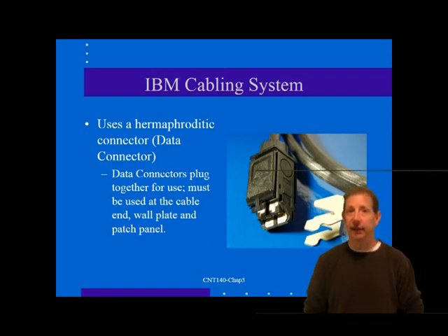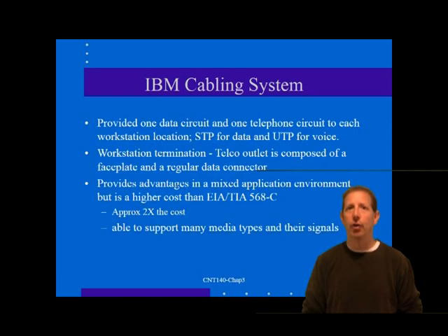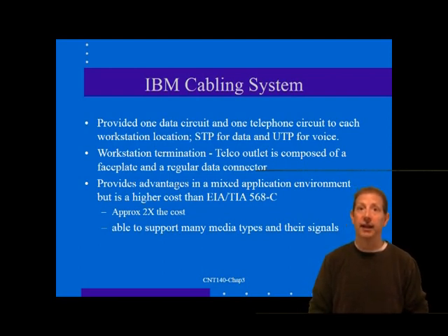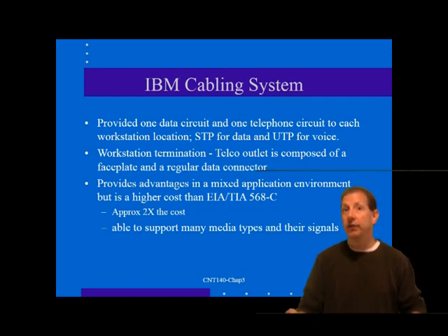The unique data connector was probably designed with token ring in mind, since that has long been IBM's network of choice. It contains a mechanical shorting bar mechanism that can electrically loop back a cable or jack when it's been disconnected, an operation very similar to that of the token ring MSAU port.